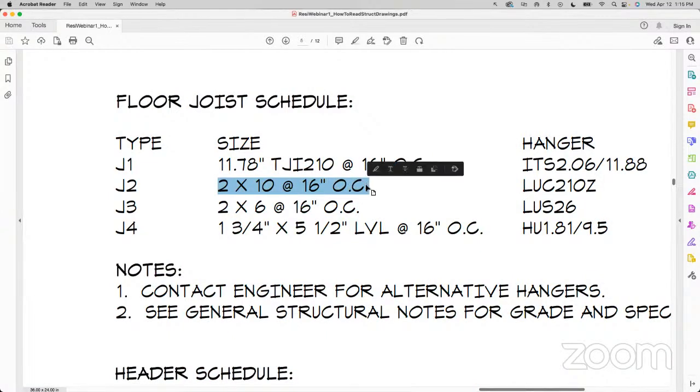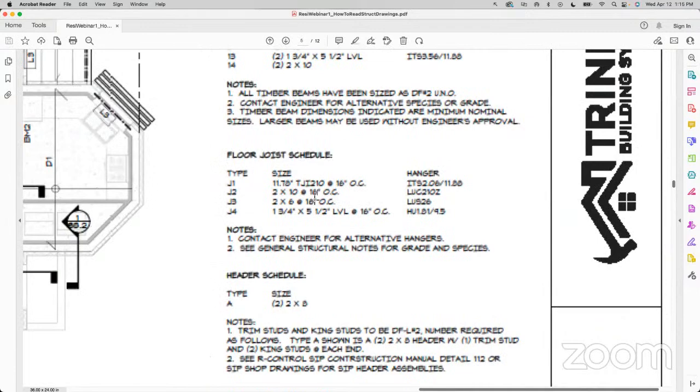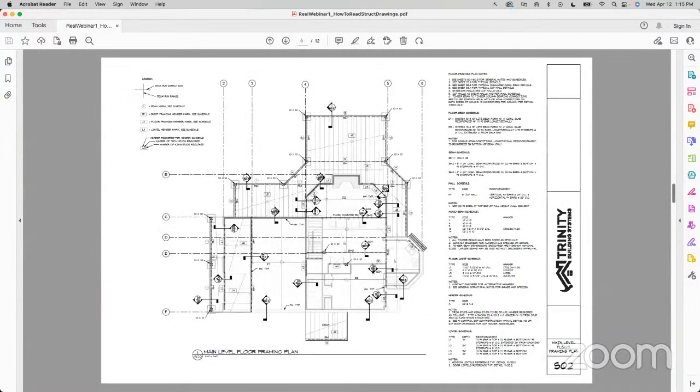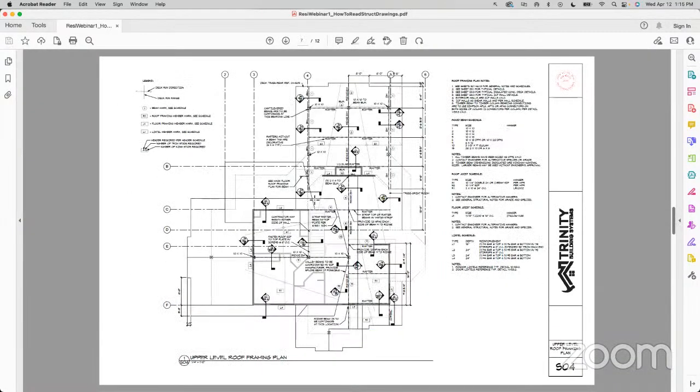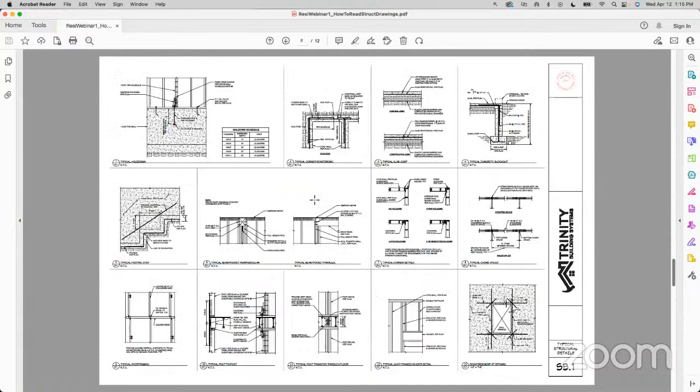So we can assume that those rim joists are 2 2x10s back to back because it's telling us that there's 2 rim joists. Now, because we all like to be confusing here, a 2x10 we know actually isn't 2x10. That width, instead of being 2 inches, is 1.5 inches.